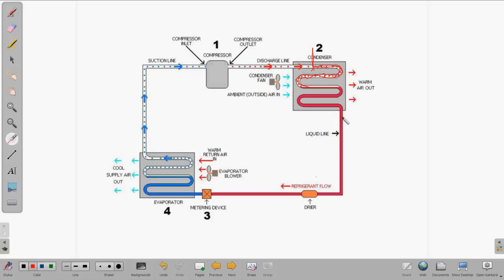Now, when you're measuring superheat and subcooling and trying to check a refrigerant charge, you should go in and check the metering device, but to really just get a quick look, I always use subcooling, because it doesn't matter whether it's a fixed metering device or a TXV. If this system is overcharged, it's going to back up behind the metering device no matter what.